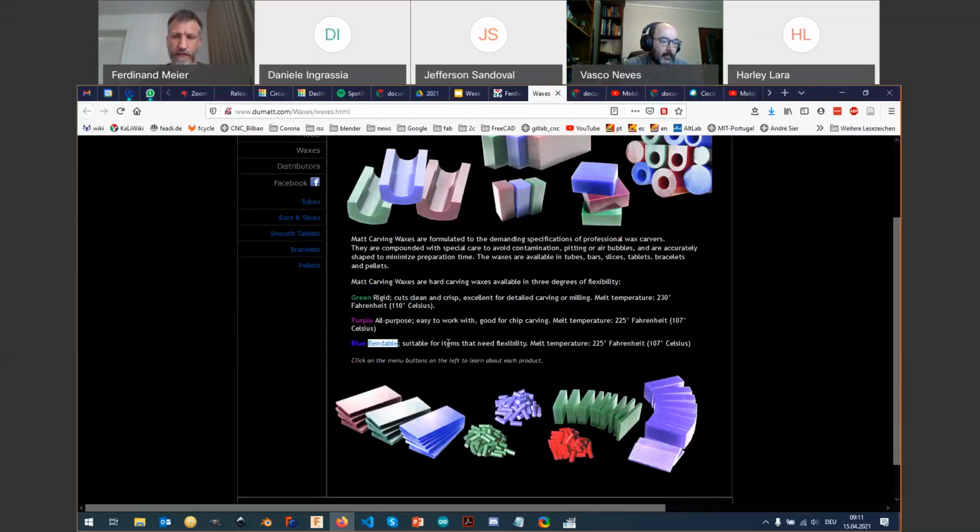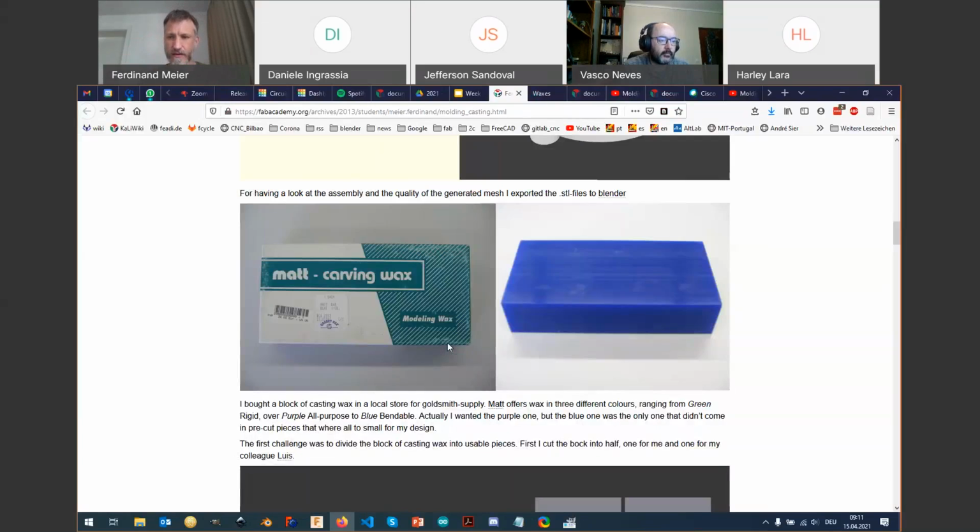You should be very careful to clean your whole working space, your whole milling machine, so that in the end you can collect all your chips and cast them into a new block. Casting the new blocks is not as easy as it sounds. I had many failed attempts because you basically need a metallic form to cast it into. If you make it from wood, it will degas and you will have bubbles. If you stir it with a wooden stick, it will make bubbles.